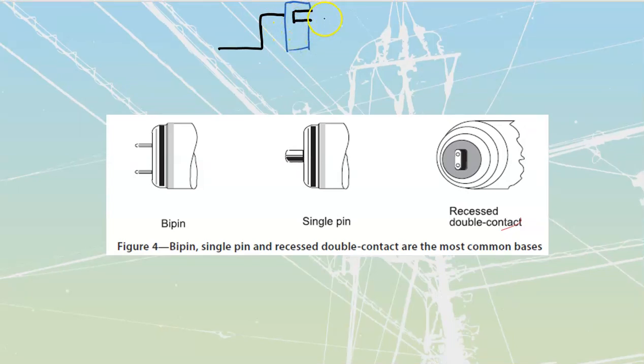so that's my tombstone inside there. That wire goes up on the inside. When I press this lamp into this tombstone, it moves that cup back, and that allows it to actually make contact with the line in. Let's draw that like that. When we insert that inside there, that line in is then carried through into the ballast, so that when you remove that lamp, the ballast should be dead. Now that's provided that lamp is still wired correctly.